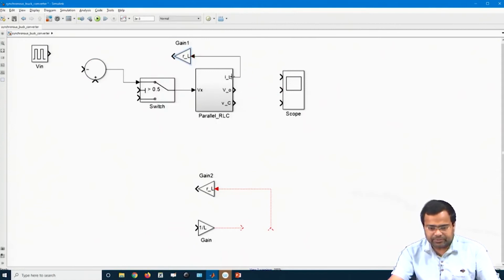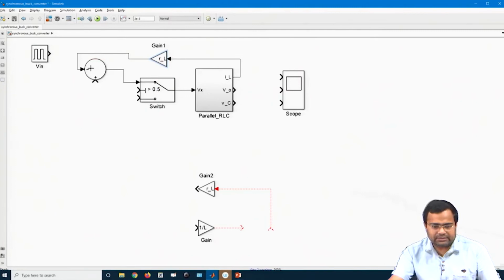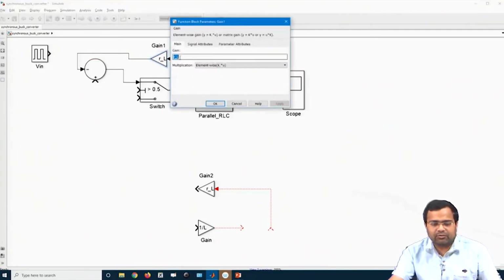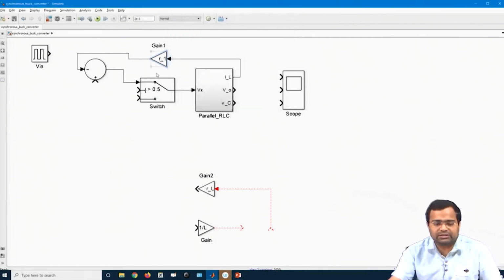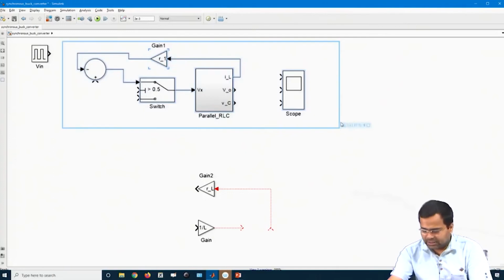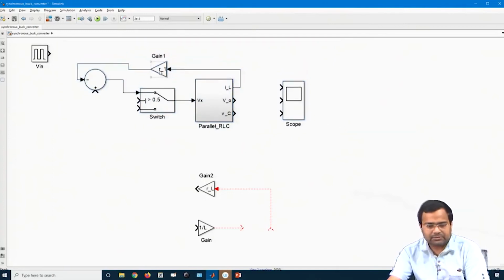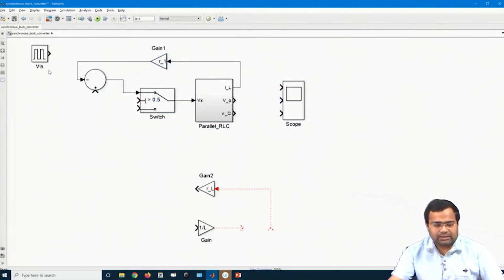This is coming from the inductor, we can simply connect it like this, and this is my R1, or R underscore 1, that is my on time resistance of the high side MOSFET. And this is now my new V in.